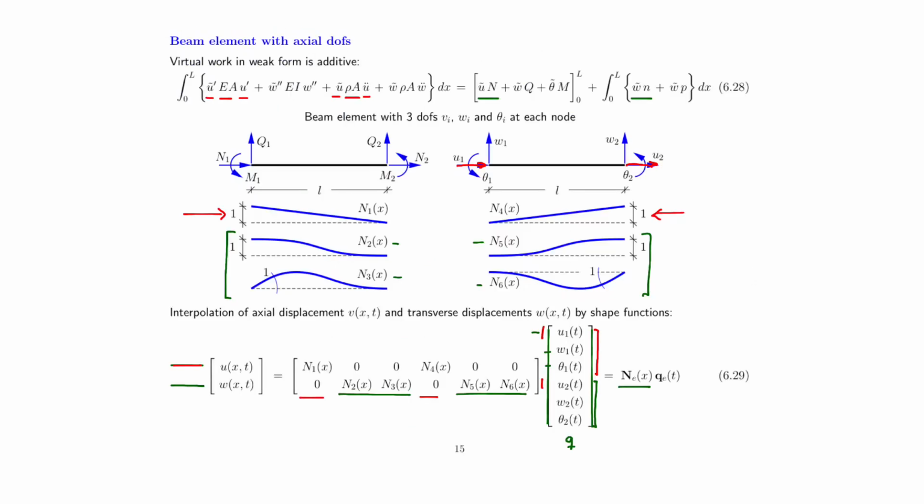So therefore, using these 6 shape functions in this format, the N function will be a 2 times 6, and thereby both K and M will be 6 times 6 matrices. And if we substitute our shape functions in the integrals on the previous slide, we will directly, by numerical or analytical evaluation, get a 6 by 6 matrix.